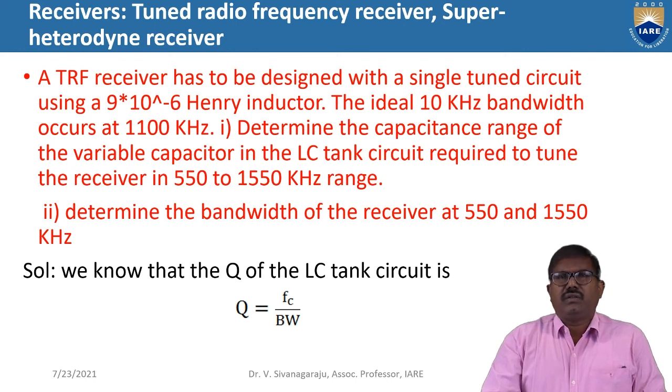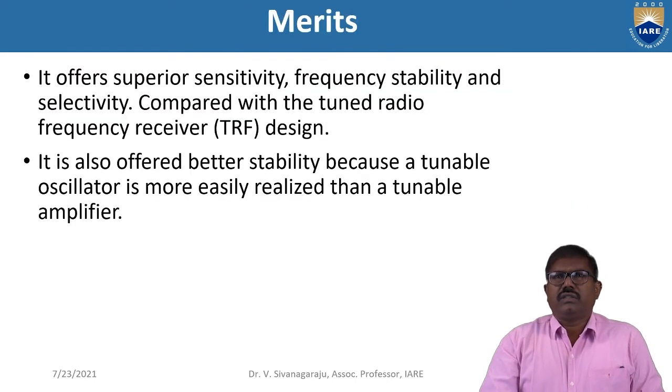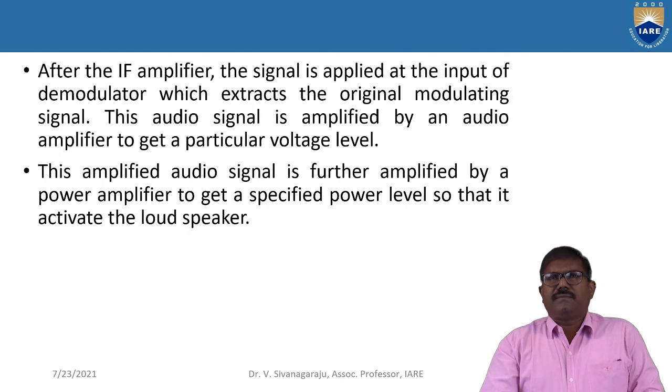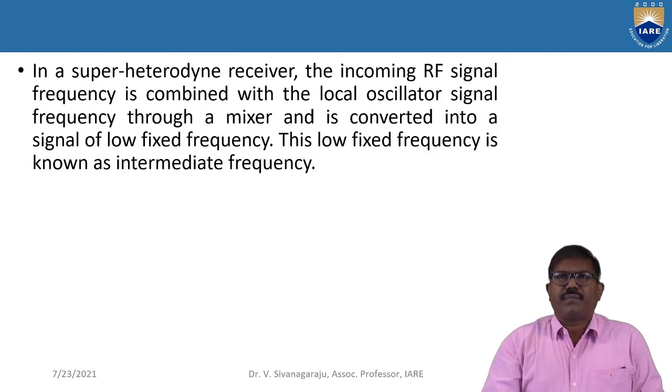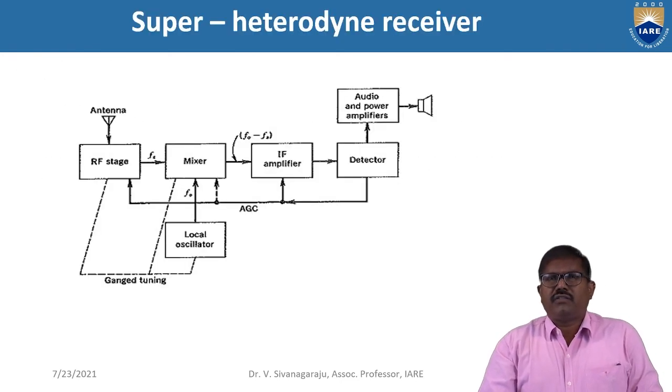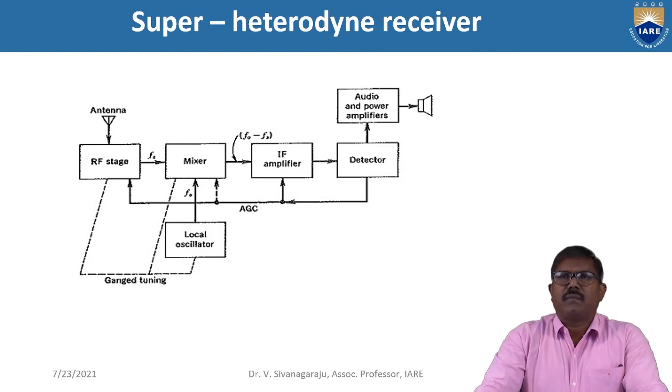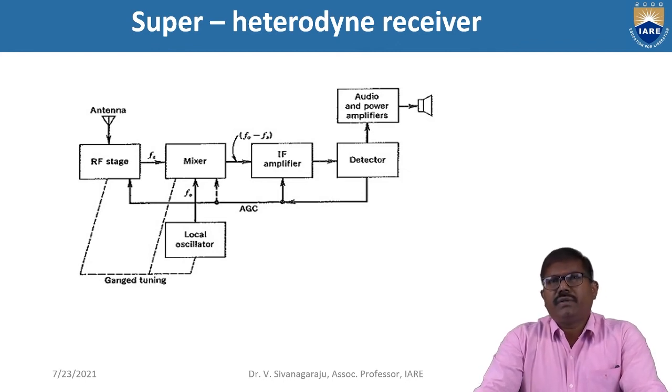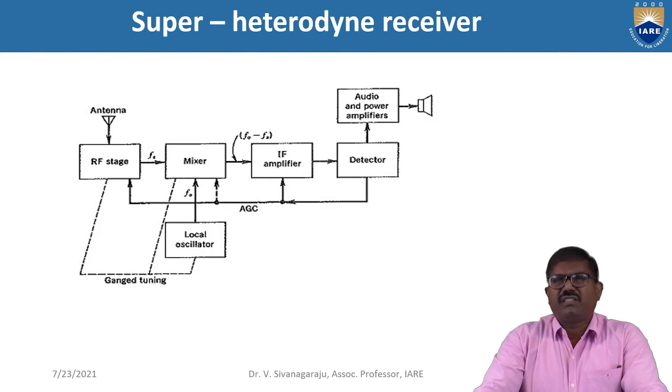Once again, let us see the super-heterodyne block. In this block, we have an RF stage, mixer, IF amplifier, and detector.